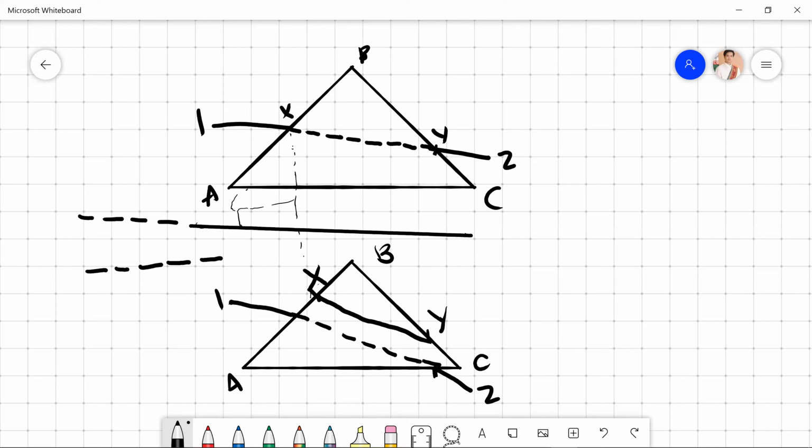Okay, on visibility, that's a good question. Regardless of whether there is a piercing point or not, you must draw the correct visibility. And you need the correct visibility every time you have overlapping planes and lines. A plane and a line, a line and a plane, or a plane. There's no visibility when it's only lines. So as long as a plane is involved and there is overlap, we automatically have visibility.